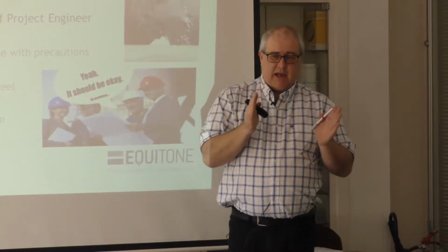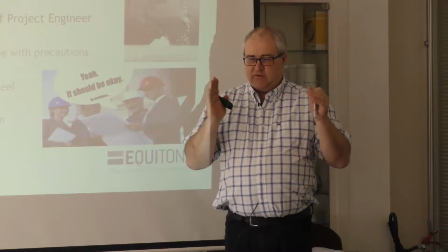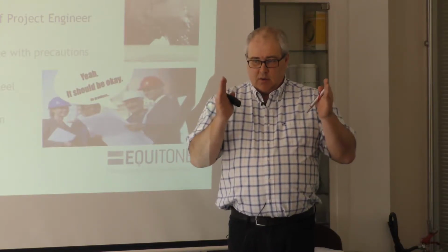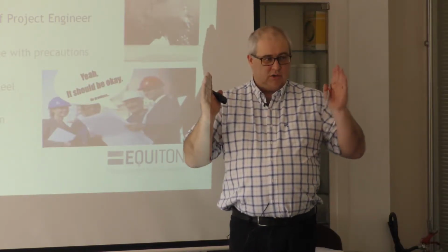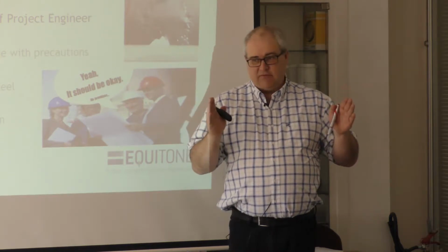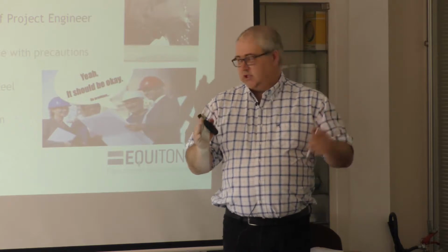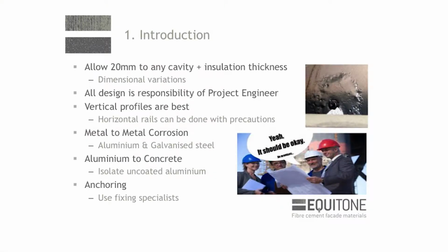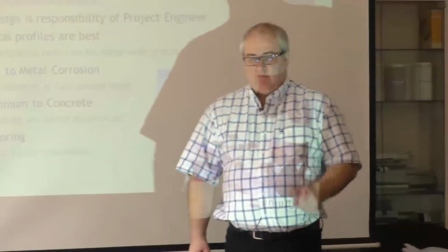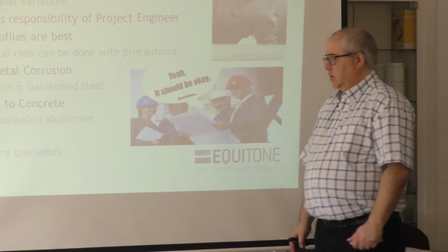Now please remember that, because after lunch when we're talking about how we fix our systems, we are fixing some of our uncoated raw cement boards to aluminium frames. Okay? But our fixing system deals with this issue. And when it comes to anchoring, use fixing specialists. Who would be the best guys for anchors here for the wall? UPAT. UPAT, yeah. Or Fisher. Fisher. Yeah, we work a lot with Fisher.